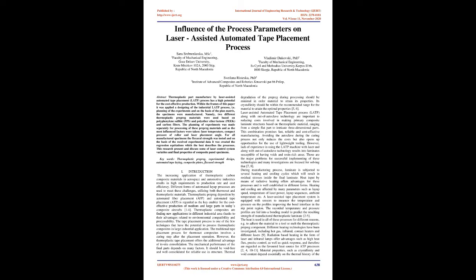The mechanical performance of the final parts depends on many factors. It should be void-free and well consolidated for reliable use in structure. Thermal degradation of the prepreg during processing should be minimal in order for the material to retain its properties. Its crystallinity should be within the recommended range for the material to attain the optimal properties.